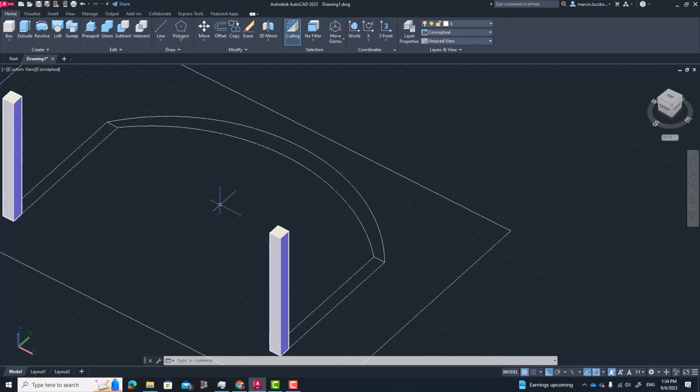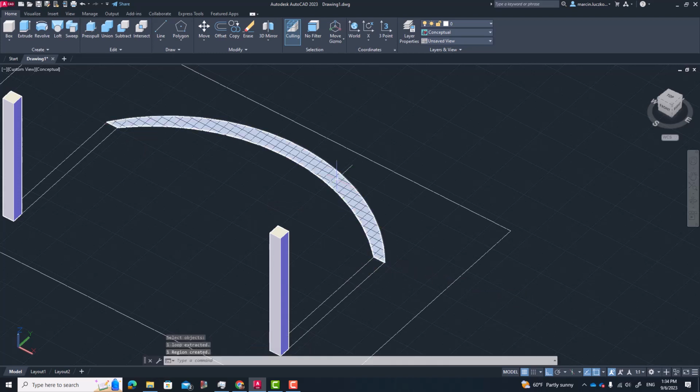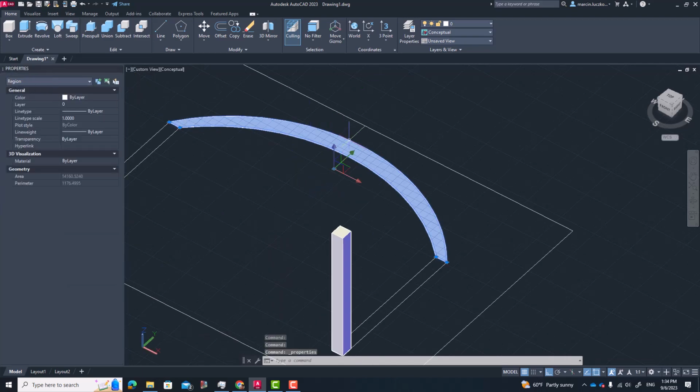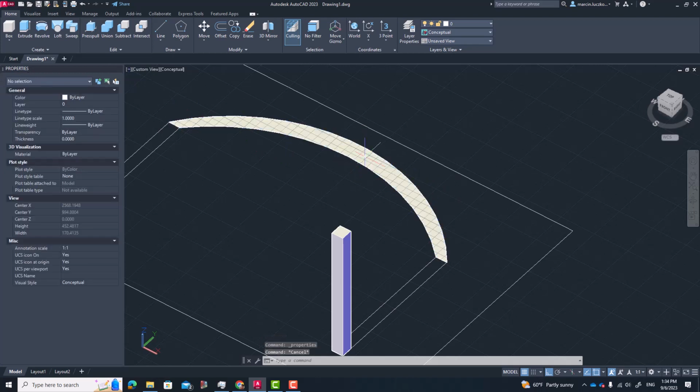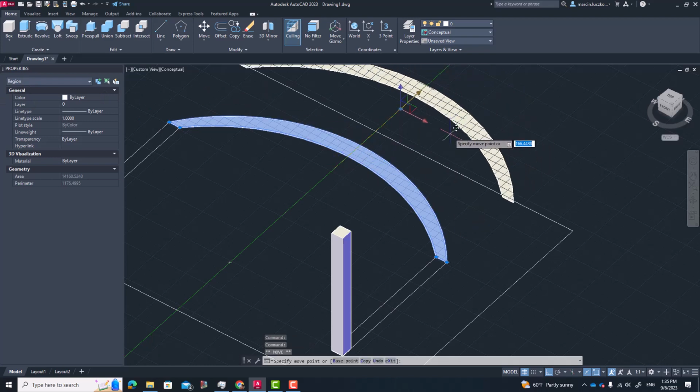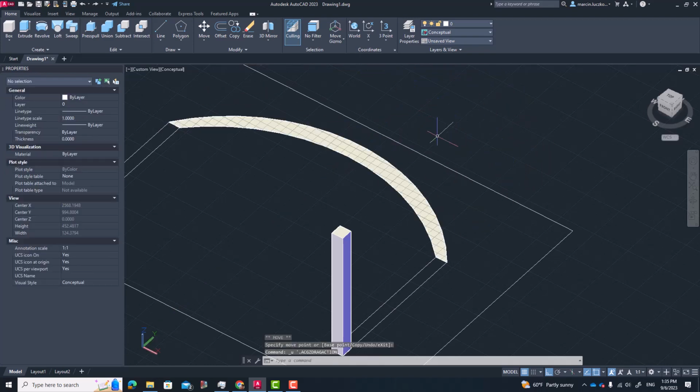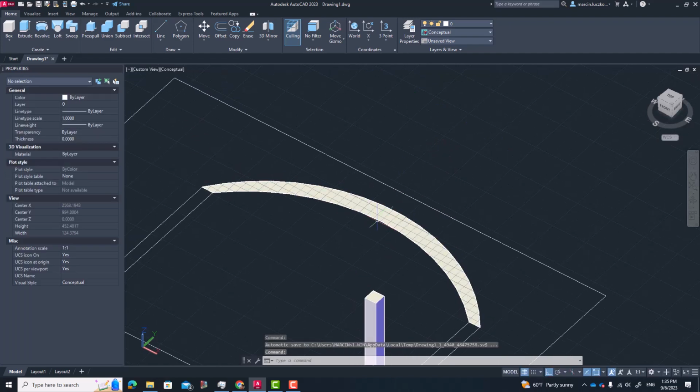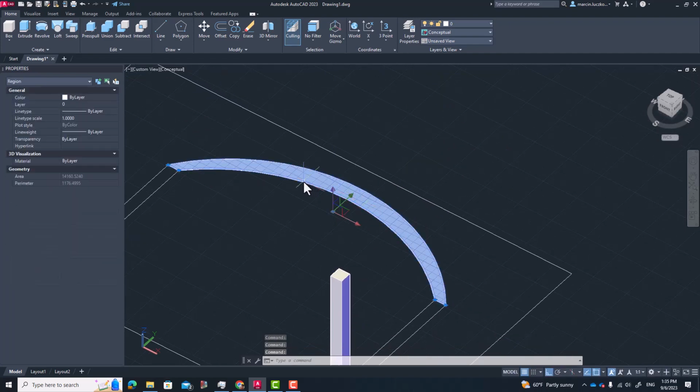What can we try to do is, for example, to create a region. I type region. I now am collecting four elements and I am approving. So now I have something. I can check what is it. I use the shortcut Ctrl+1, which I was explaining before. It opened the properties. If I will click right now, I see that this is a region. I will move it up somewhere here. Oh, sorry, I will maybe stay with it as it is right now, just to explain one thing.